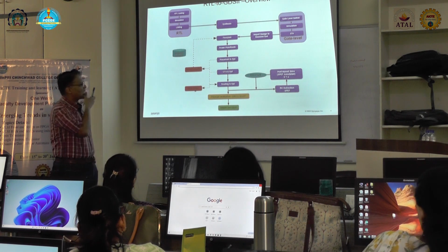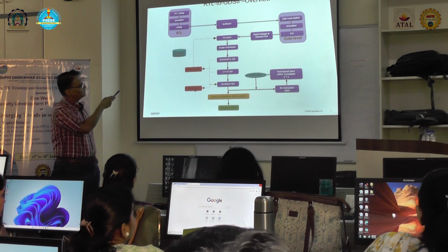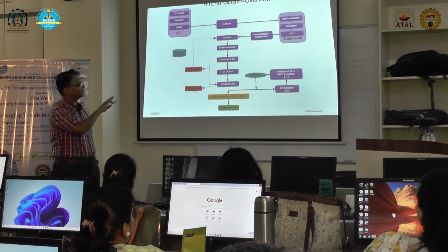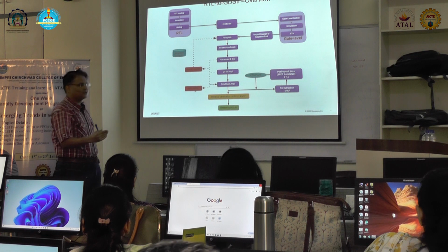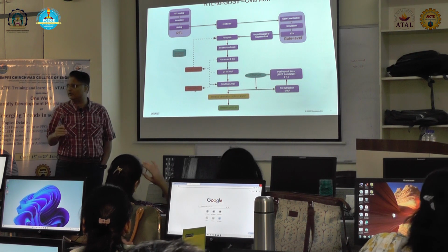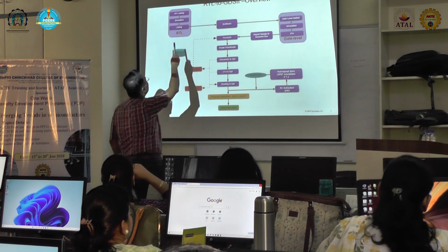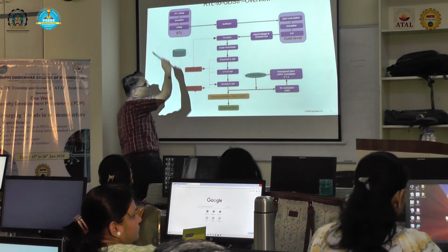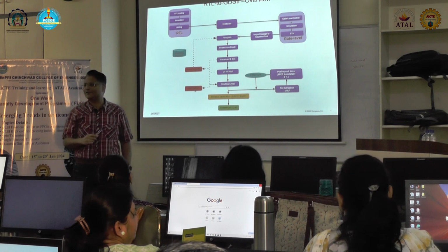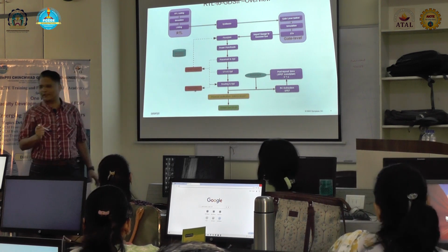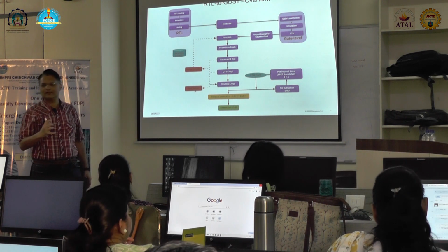Most of the times, if physical design has done its job correctly and you are still seeing static timing analysis failures, then you need to update the RTL, which means that you have to start from the top again. So it's a long loop. So you will use time.